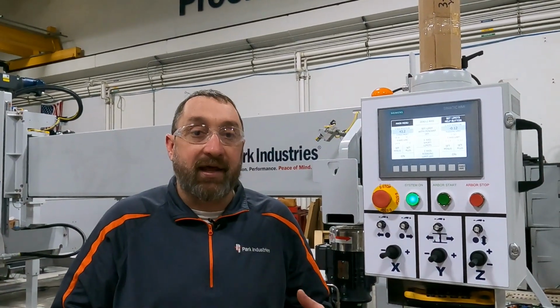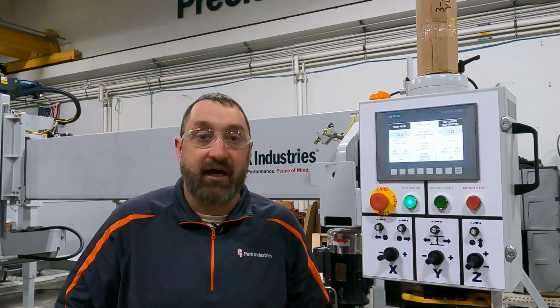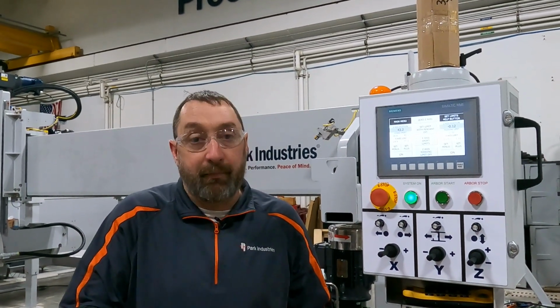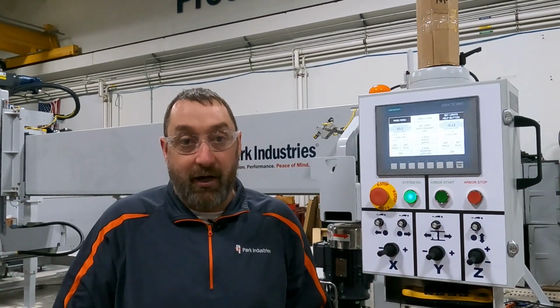That works very well if you're doing auto cutting and let's say you're cutting up a half slab and you want to just rip backsplashes. You can set up your auto cuts and only cut half your table, so you're not waiting for the auto cuts to utilize the full table. That's kind of how you use the set limit screen.